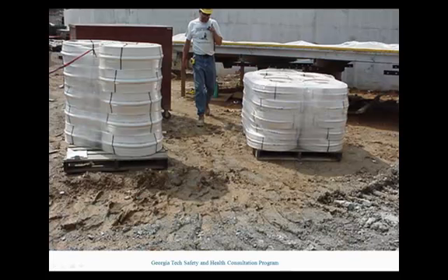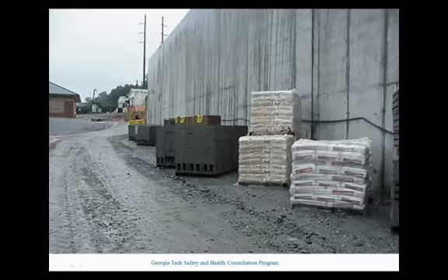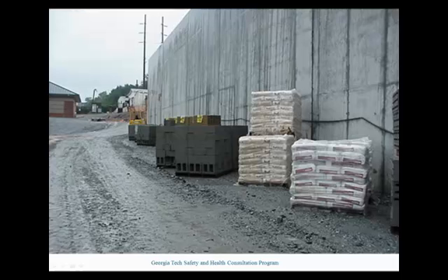Aisles and passageways must be kept clear and in good repair to provide for the free and safe movement of workers and the operation of material handling equipment. For storage of bagged materials, the bags must be stacked by either stepping back the layers and cross-keying the bags at least every 10 bags high, or wrapping the stacks with a strong plastic material to prevent them from falling.